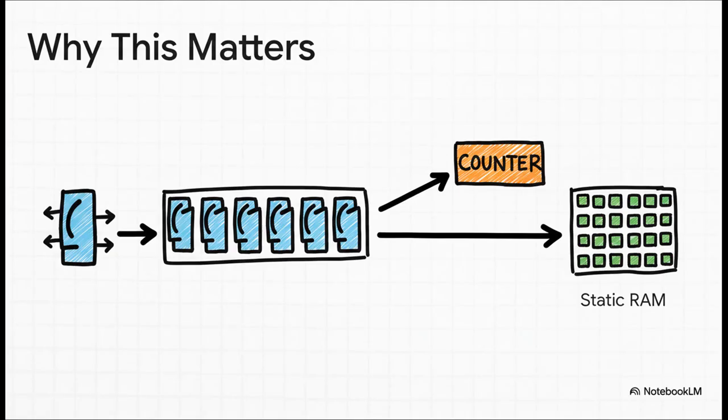It matters because everything digital is built on this foundation. You group a few of these flip-flops together, and you get a register that can store a number or a letter. These registers act like little holding pens for data, letting your computer's brain move information around without losing it. They're at the very heart of any circuit that needs to count things, and they are the absolute basis of the fastest type of computer memory, static RAM.